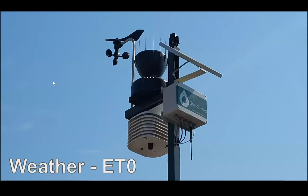We also have weather, of course, a crucial part of irrigation. We put weather stations. We're tied into CIMIS. We're tied into other common weather station brands through APIs and other methods. We also have weather sensors that are locally installed in the field. That way we can get all the rainfall information, temperatures, frost alerts, and of course, for irrigation purposes, ETo, that we're gonna see in the upcoming slides.